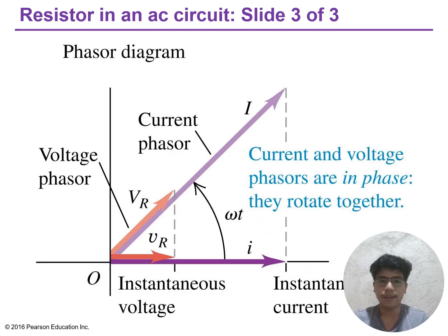By observing the peaks of voltage and current occurring at identical times throughout the plotted time, we gain an intuitive understanding of what in phase means. There is no time delay, no separation between the voltage driving the circuit and the current responding to it. This instantaneous response is possible because a resistor has no ability to store energy. It cannot accumulate electric charge like a capacitor or magnetic energy like an inductor.